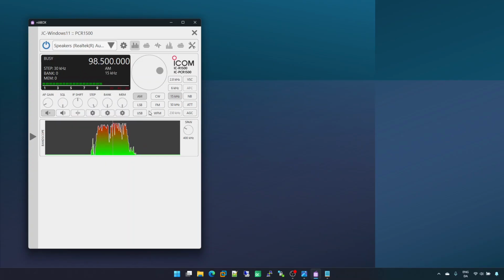Here we have the band selectors, which are the usual ones in any kind of receiver. We have AM, lower sideband, upper sideband, CW, FM, and wide FM. Also, we can select here the filter frequency, the modulation frequency. It depends on what band you are using; the different filters available will change. This is similar to what you get if you are using the Icom software for this type of receiver. I will move to WFM 230 kHz.